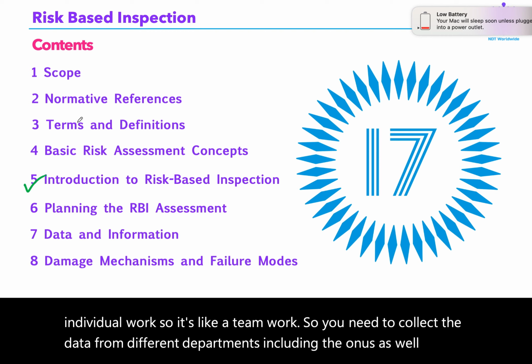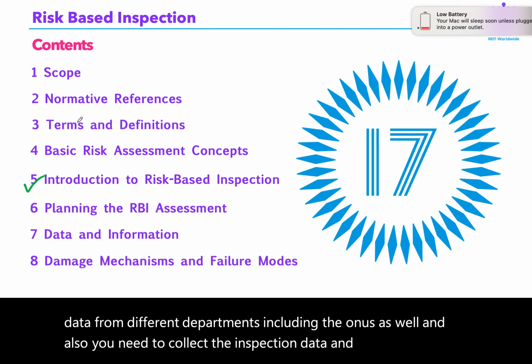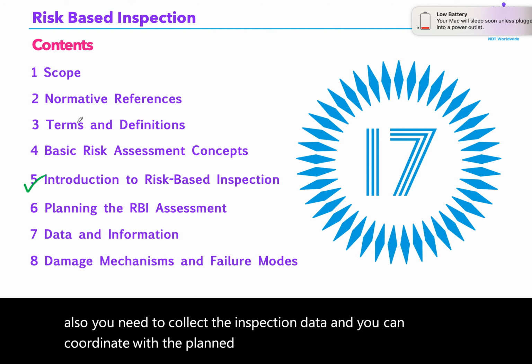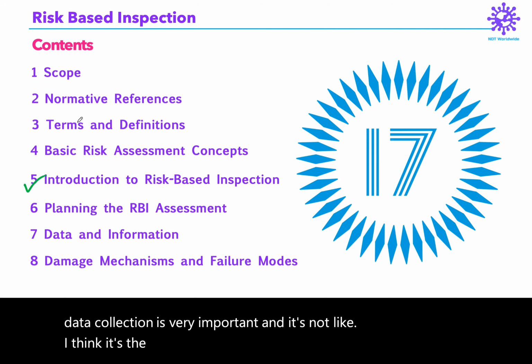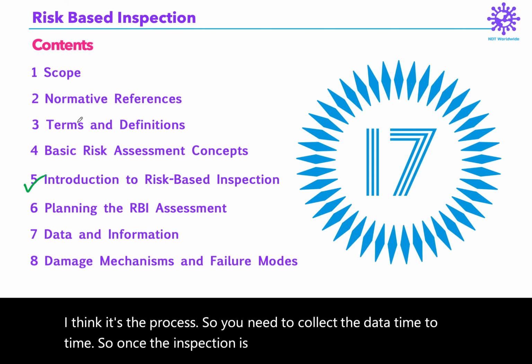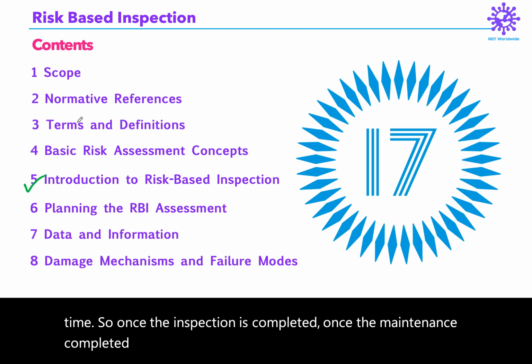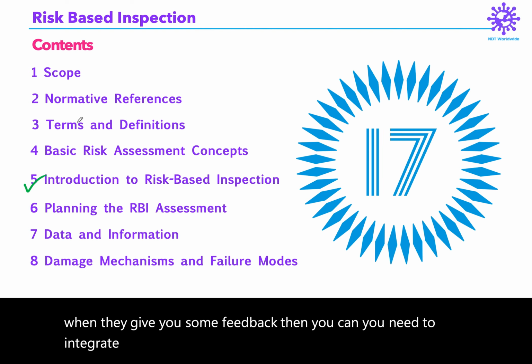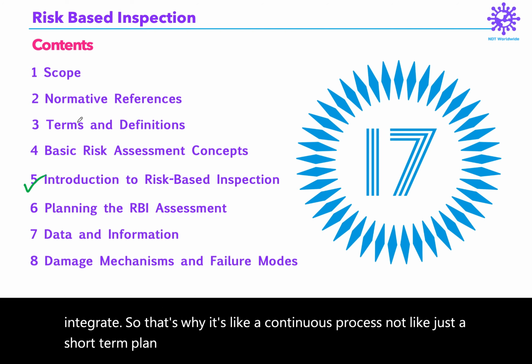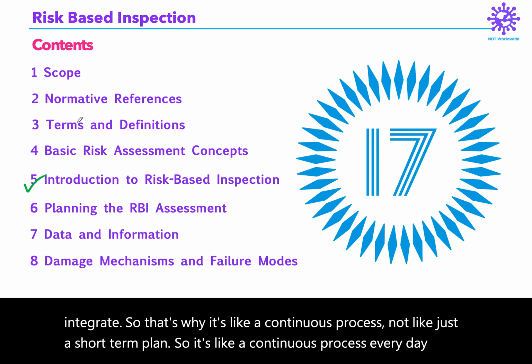You also need to collect the inspection data, and you can coordinate with the plant operating personnel. That's why data collection is very important, and it's not a single step process. You need to collect the data from time to time. Once the inspection is completed, once the maintenance is completed, or when the safety people or operating personnel give you some feedback, then you need to integrate it. So it's a continuous process, not just a short term plan. It may be every day, or weekly, or yearly.